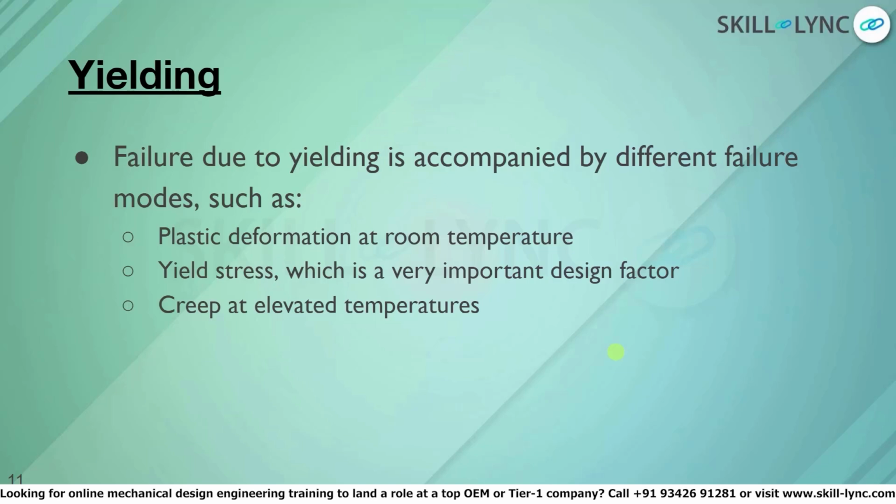Next, we'll see creep at elevated temperatures. Sometimes, even though the stress is below the yield stress, creep can be a very important factor which we have to consider. Due to elevated temperatures, even within the elastic range, the material can undergo creep, which is again a failure. We'll be looking more at creep at the end of this session.